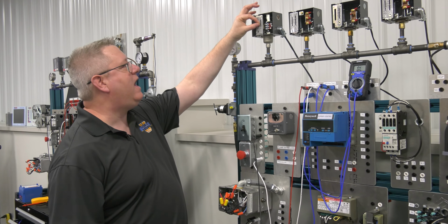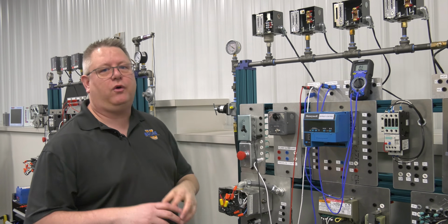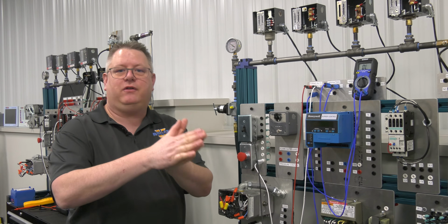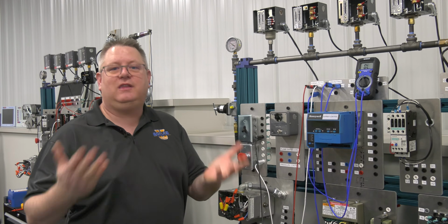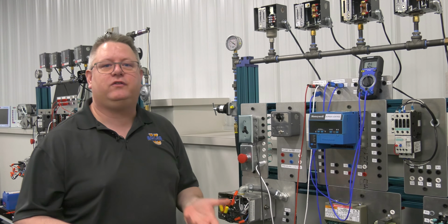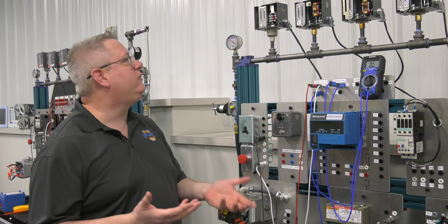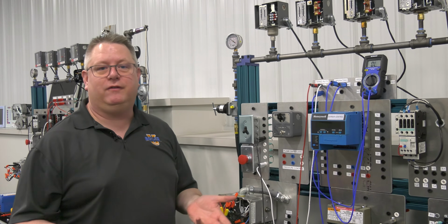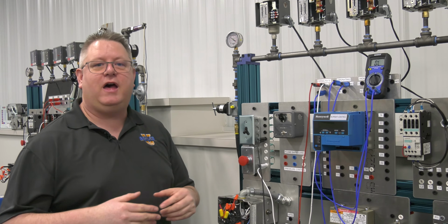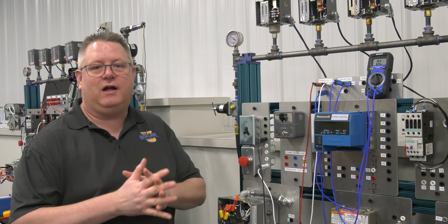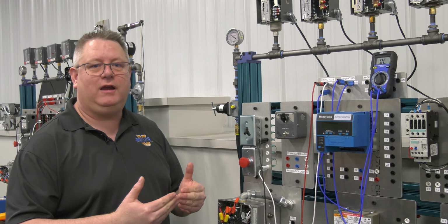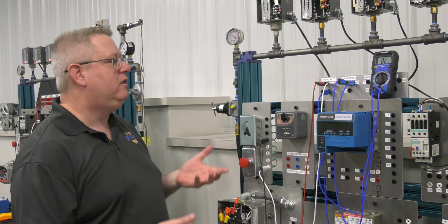Ideally, we will set that differential across the widest practical band, because if we begin modulating down at 75 PSI, we may easily be able to withstand 150 PSI on the boiler if it's its maximum allowable rating, but we don't necessarily want to run the plant up to 150 before we shut the boiler down. So we're going to pick a range that we want to modulate over that gives us as broad a range to modulate as possible, because that's going to give us a more stable and slower modulation rate, which is going to be appreciated by the burner.